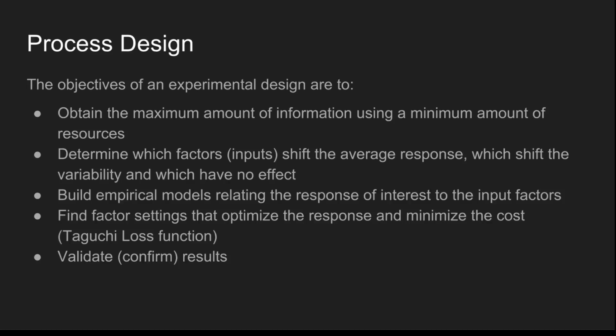Because of this, each factor can be assessed independently of all the other factors, so the effect of one factor does not affect the estimation of a different factor. This can reduce the time and cost associated with the experiment when fractionated designs are used. There are 3 noise factors in this example: ambient temperature, moisture content, and percent regrind. There are 2 levels of the 7 controllable factors. Most controllable factors originate from the machine which is used to produce the product. Noise factors primarily originate from the product's materials and environment of production.